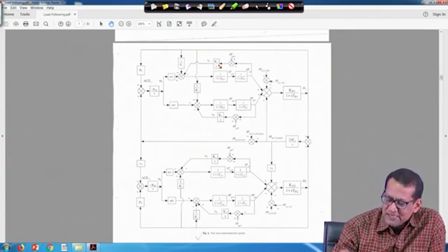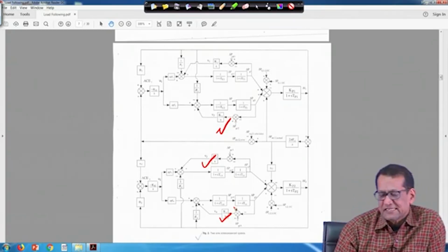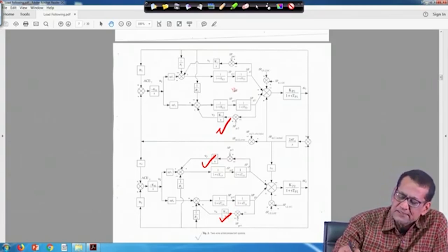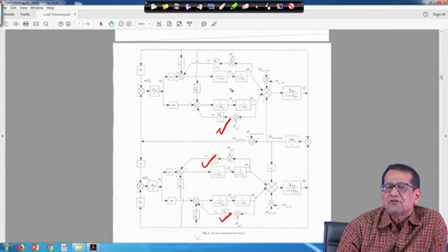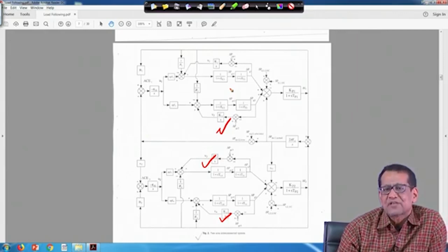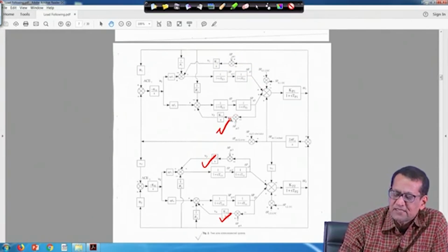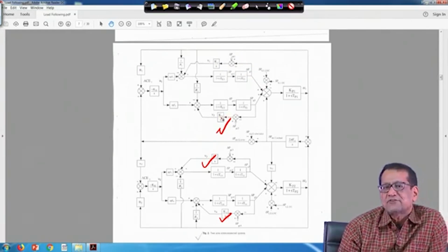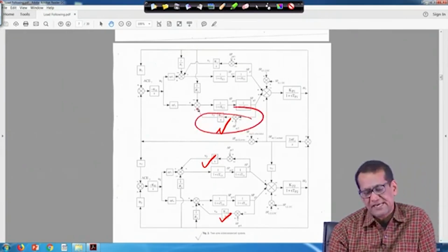Similarly, here also a load following controller is there. But there is no need that every generating unit needs a load following controller; it depends on the system, right. Suppose this unit may have a load following controller because some discos have a contract with it, and this unit may have no contract with any discos, right. So, in that case this will be in AGC.